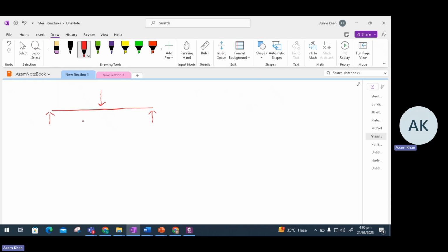That is our structure. In structure analysis, we must develop an understanding of the transfer of force and an appreciation for applied loads and dimensions. So what do I mean? I mean that if we have, for example, a 30 kilonewton load applied onto a beam, and this beam, imagine, is say 3 meter and 3 meter. First of all, we must understand what type of structure is used to transfer this load. In this case, it is a beam, and we know that a beam is a horizontal member which transfer the load to the support points.